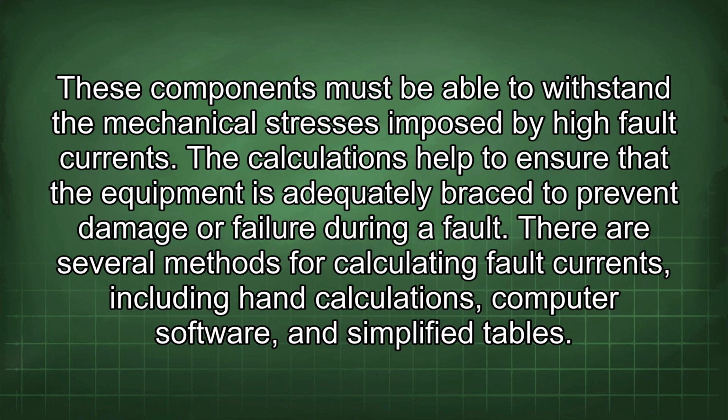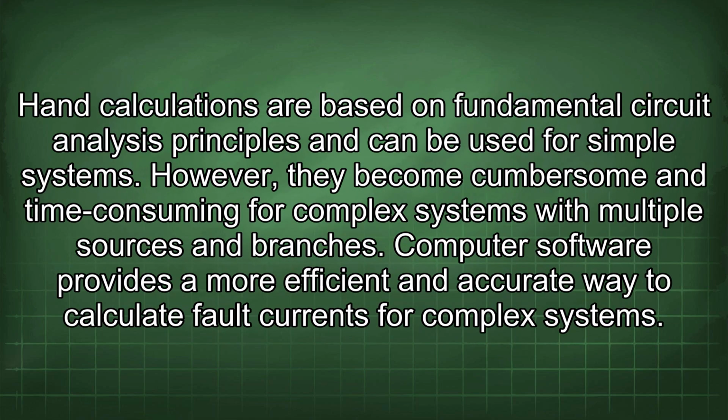There are several methods for calculating fault currents, including hand calculations, computer software, and simplified tables. Hand calculations are based on fundamental circuit analysis principles and can be used for simple systems. However, they become cumbersome and time-consuming for complex systems with multiple sources and branches.